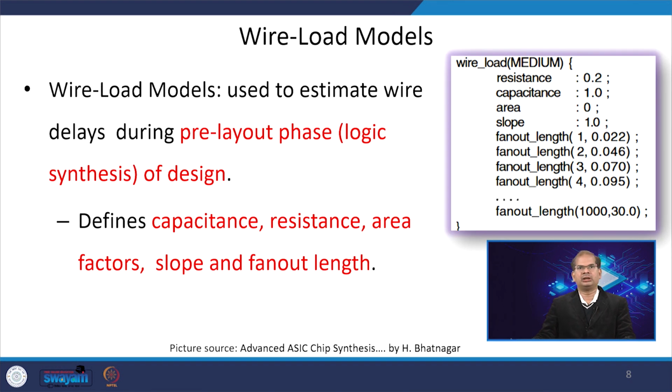Now, we will discuss that interconnect model, which is stored as wire load models actually. Okay. So, this is stored as a wire load model. If you can see here, this is the wire load. Okay. Then here a wire load model is specified. In this one, what we are doing is estimating the wire length. When we are designing a chip, we need to pre-estimate the wire length, and it is used during the pre-layout phase or logic synthesis phase. Whenever the layout has not been done, we can use this wire load model to estimate how much delay can be possible due to the wire loads. That will help us to predict how much slowdown of the delay can be possible in the final layout. So, we can budget for that.